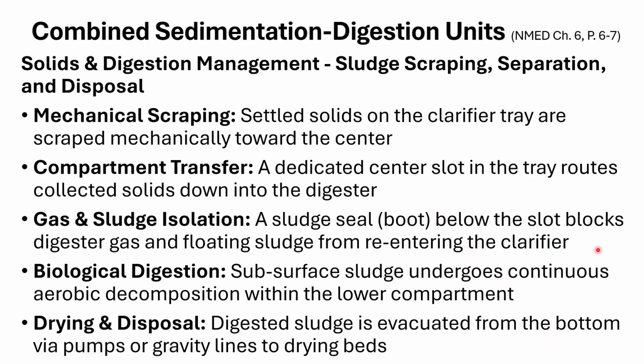And we're going to have a sludge seal below that, and it's going to prevent digester gas from going up into the clarifier. That is what the seal is going to do, as well as prevent any sludge rising into that clarifier and causing us problems. So that's why we have a boot seal there.